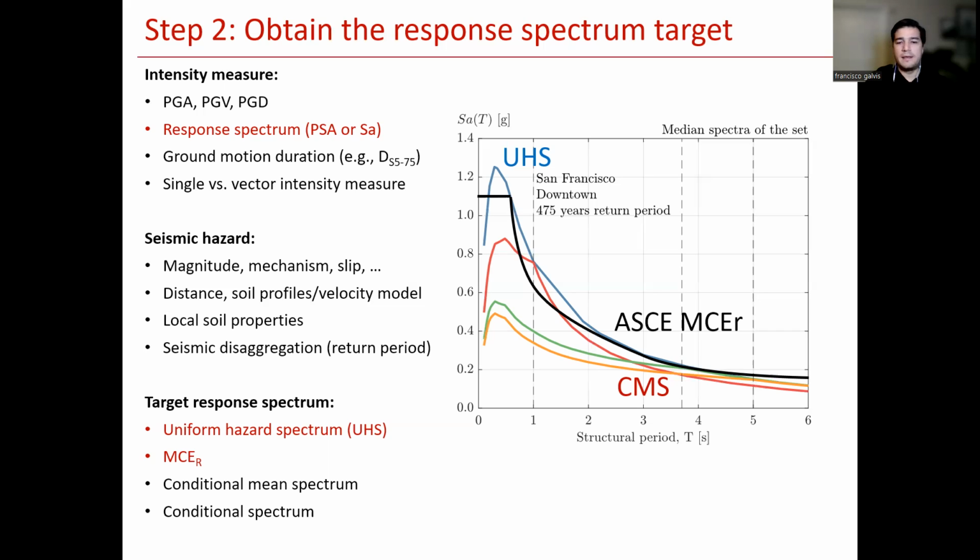And there are other metrics like the Arias intensity and other things like that that are important for measuring the intensity, right? Because the whole idea here is that the earthquake in reality is a time series, right? It's an acceleration time series that we are trying to simplify with a few scalar numbers. And one of those is this response spectrum.